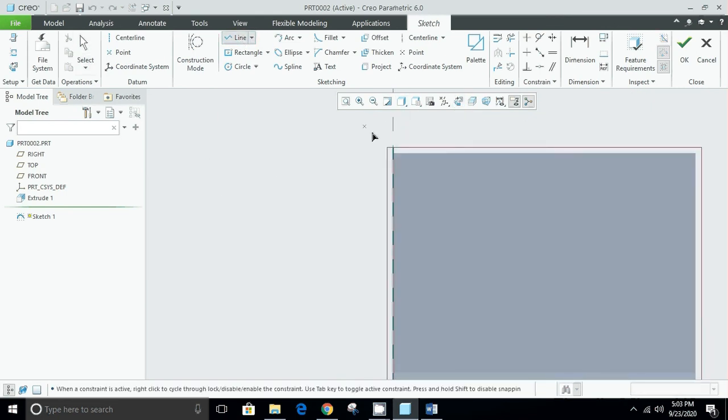For example, if I select a line, and from this point till this point and this point, and then I use the fillet command, and give it some radius, for example 3 units, and then I use this line in order to join this point till this corner and the other point, and using this delete segment I will be removing extra lines.